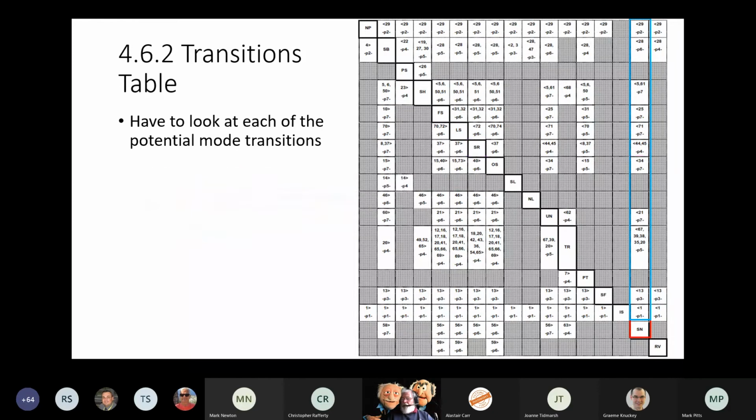If you haven't got a movement authority and you haven't selected the override, then the next option is to go to trip. And the key condition here is 39, that if the ETCS switches to level 1, 2, or 3, and there is no MA stored on board, the train will trip. And that's an undesirable action. So hence the use of SR with the override procedure using a written instruction.